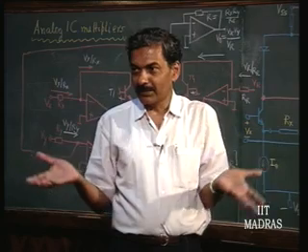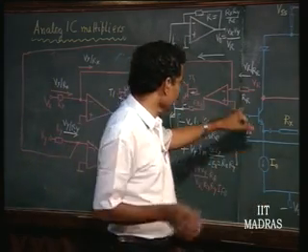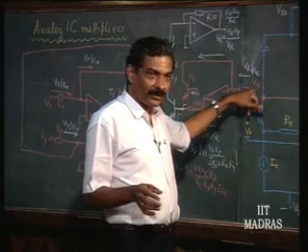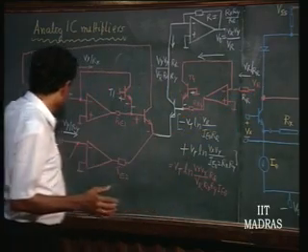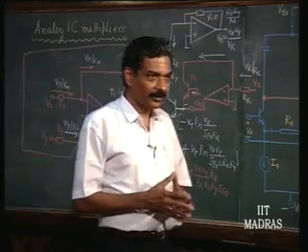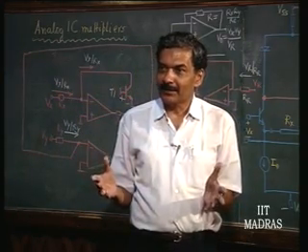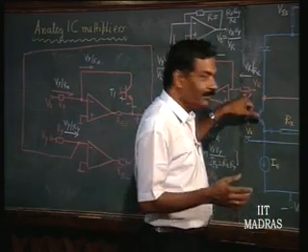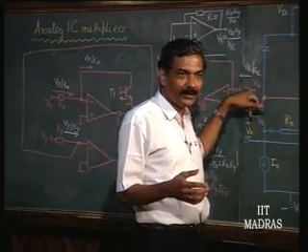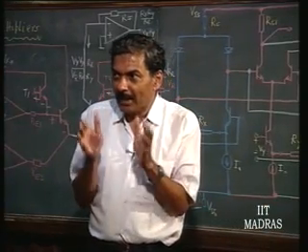V r is what you are calling your reference, which is going to be maintained constant. So, if you make V r as V y and V y as your V r, you are getting a divider. And once again, division by 0 etc. is not allowed, because you cannot go to a current which is very low here. Why? Because our assumption is that I e is equal to I e naught exponent